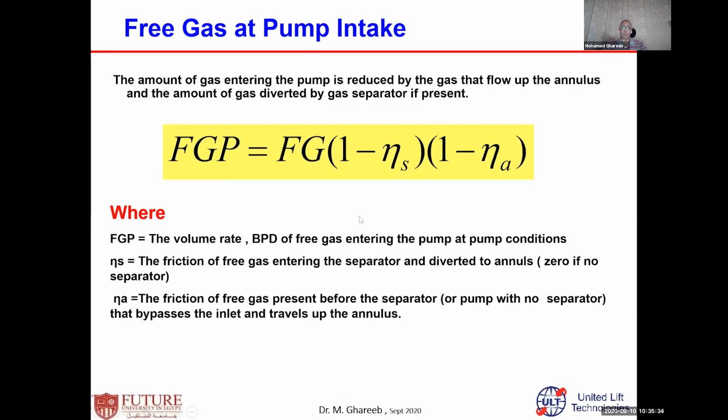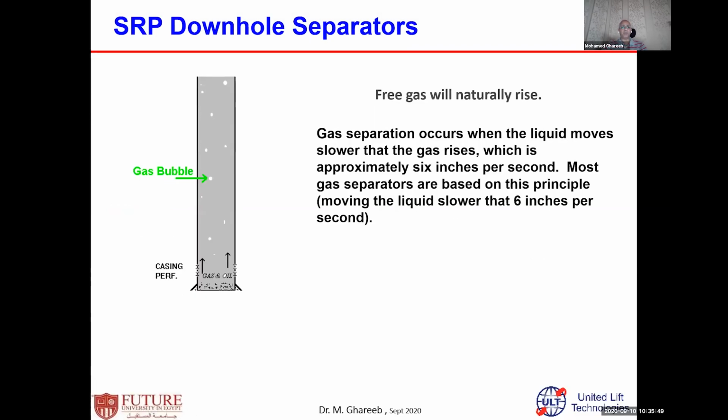How much free gas, this equation can give you the amount entering the pump, based on the volume of the gas, based on the volumetric efficiency of the pump, based on the venting efficiency of the gas, and so on. How is the downhole gas separator? You need to keep in mind how it is designed. It's designed usually based on criteria.